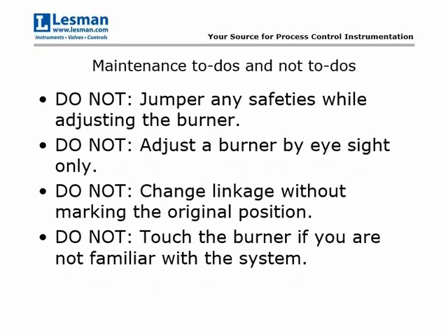At best you could get pretty close, I suppose, but again, for each application you want to verify that you have the proper setting by some kind of tangible measurement, like the air flow, fuel flow, or if you're using it on a boiler or an indirect application, you can measure the oxygen percentage of the products of combustion. Eyesight's good. You want to be able to see what's going on, especially if you're having issues, but you don't want to base all of your air-fuel ratio adjustments on that by itself.